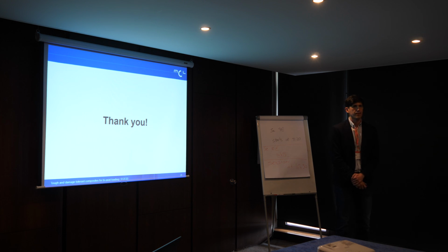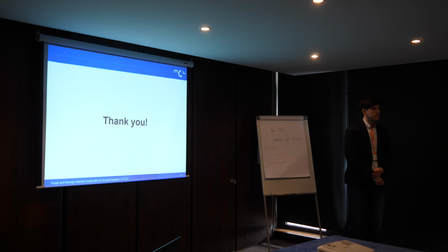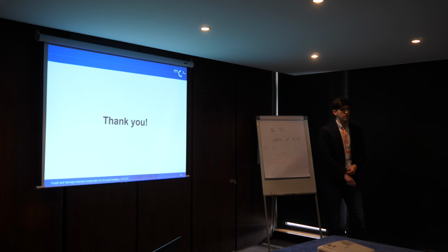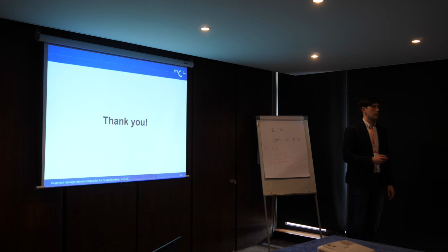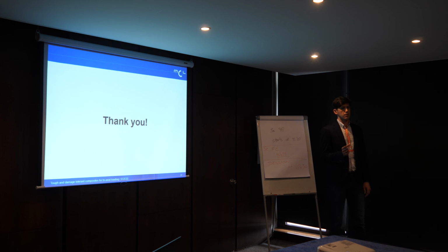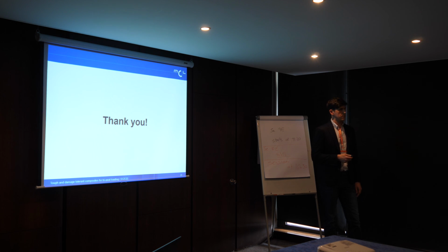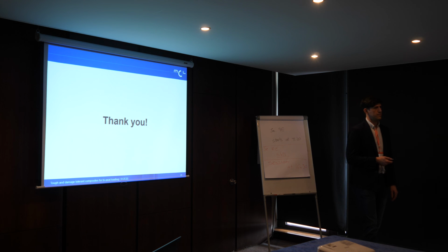Is the methodology you applied also applicable to fatigue situations with load reversal? In general, you can couple the crack propagation to any kind of loading situation you want. So you can, for example, couple the crack extension increment to the actual crack driving force. So if we have a higher crack driving force, you have a higher crack growth speed, for example. It's applicable. It's based on linear superposition.